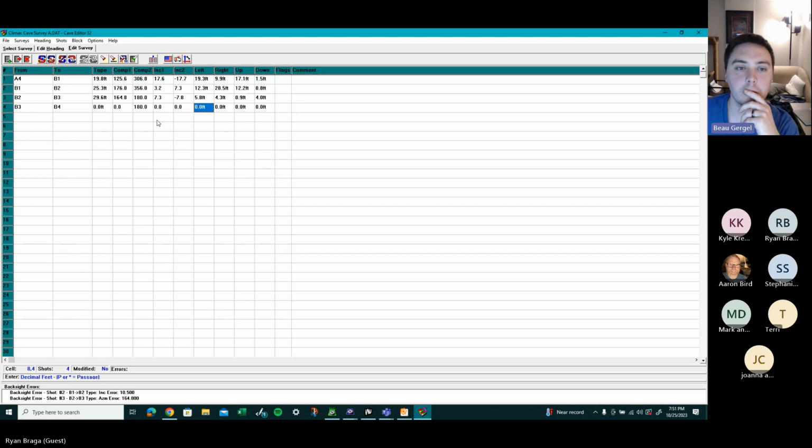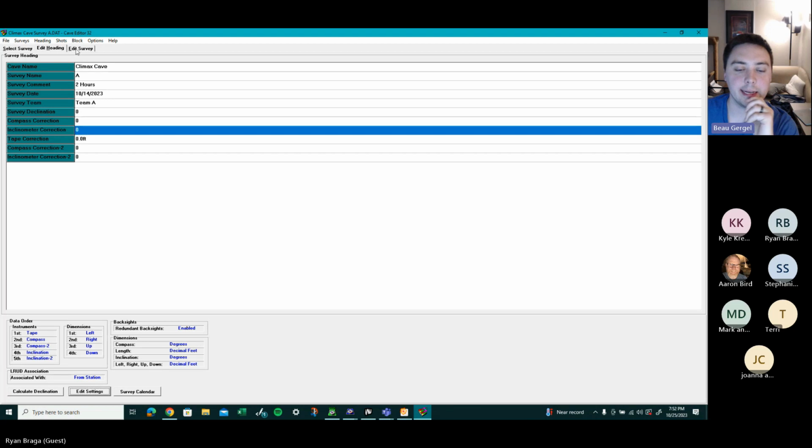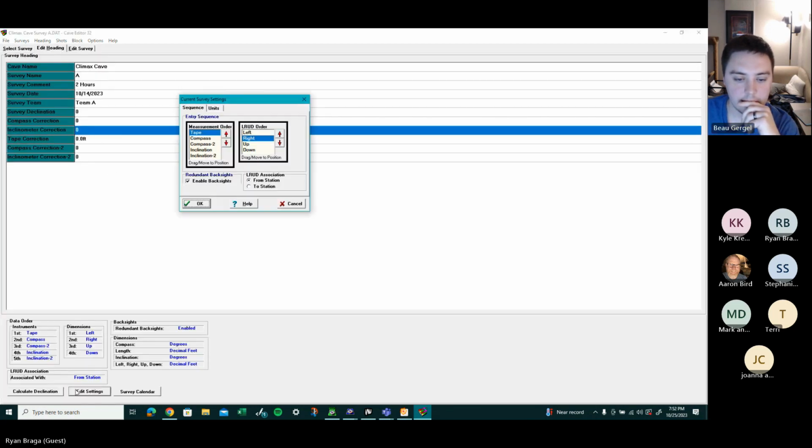Yep. And if you go back to select survey, click on the A survey, and then click edit heading. Then go to edit settings there. Where it says LRUD association, this took me a while to figure out, but they explain it on the Compass website, but you just gotta go in and dig for some of the explanations. If you click it to to station, don't do that, but on from station, it's saying, okay, remember that from station or to station, click OK.